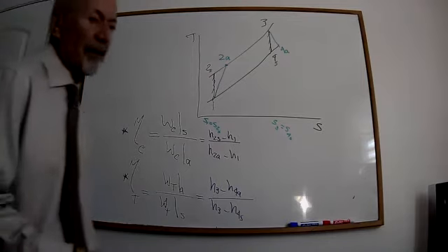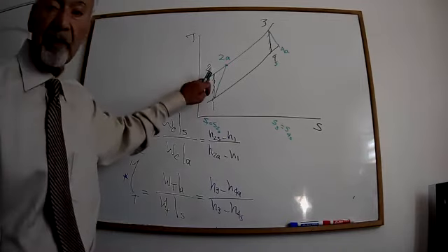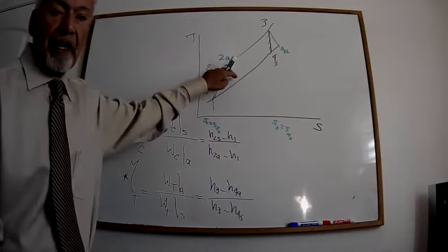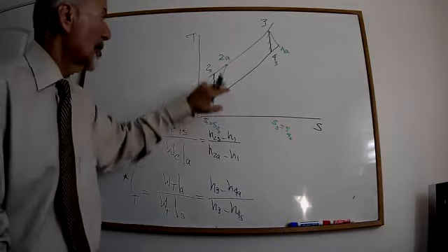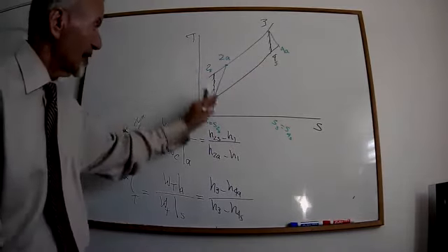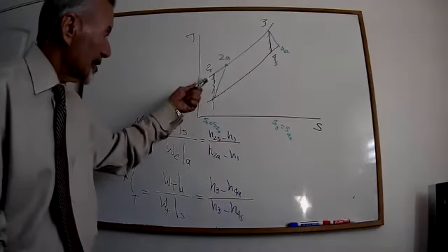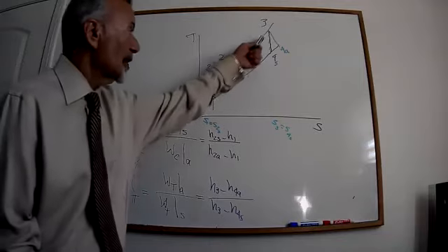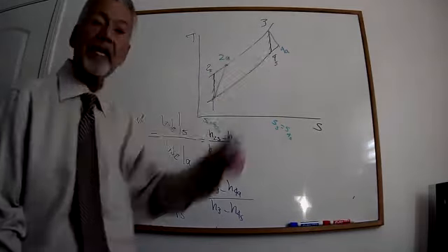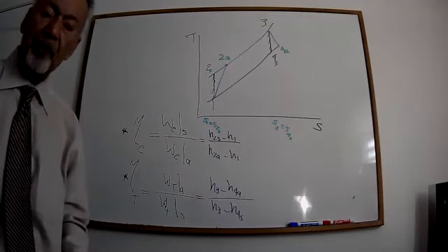The values that we find from the table, it's always isentropic values, not the actual value. Because up to now, we didn't show these green lines. We just saw everything isentropically. Now you know why I insist to dash the isentropic, because when you have these 2A and 4A, you don't get them confused. That's how you can help yourself.